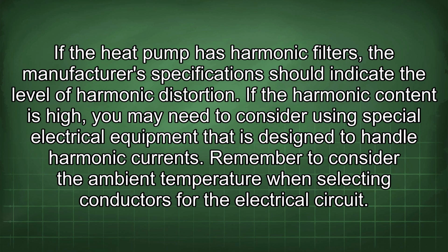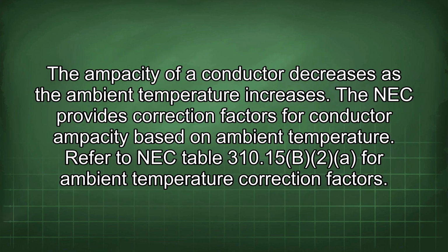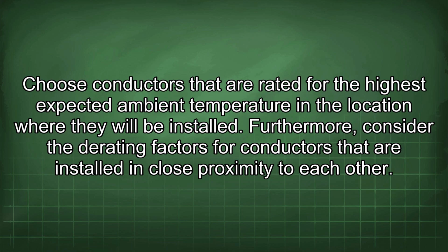If the harmonic content is high, you may need to consider using special electrical equipment that is designed to handle harmonic currents. Remember to consider the ambient temperature when selecting conductors for the electrical circuit. The ampacity of a conductor decreases as the ambient temperature increases. The NEC provides correction factors for conductor ampacity based on ambient temperature. Refer to NEC Table 310.15(B)(2) for ambient temperature correction factors. Choose conductors that are rated for the highest expected ambient temperature in the location where they will be installed.